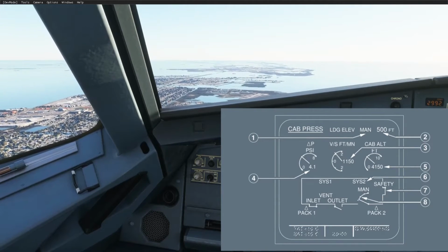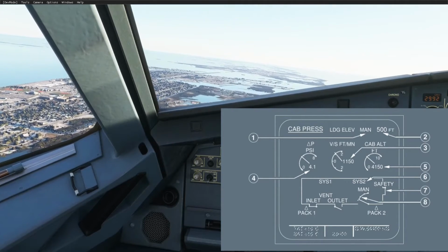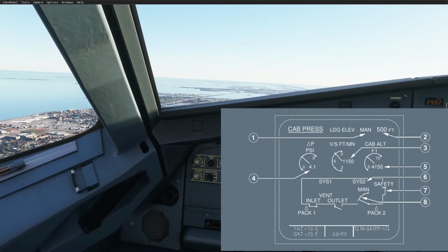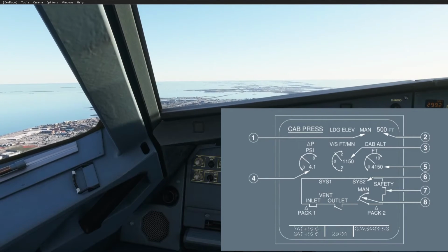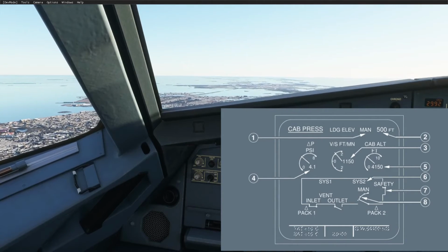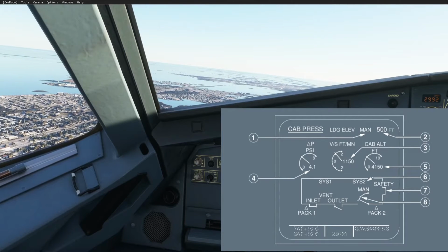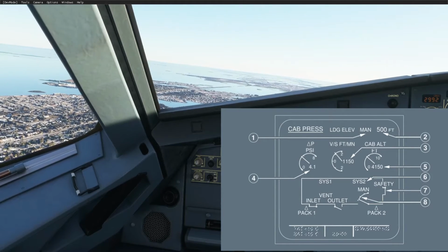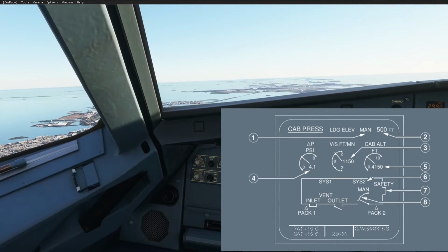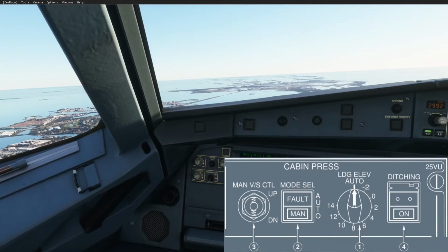And we then go into the climb phase, and during the climb, cruise and descent phase, what we care about mainly is that the rate of descent doesn't go too much. We're talking about maintaining like 0.1 psi pressure in the cabin, and we don't want any sort of climbs or descents more than 750 meters per minute really, and also we don't want to go above 8,000 feet. In the event of an aborted landing, the cabin pressure through the pre-pressurization phase will be set back to delta P plus maybe 0.1 psi, which is not that much.